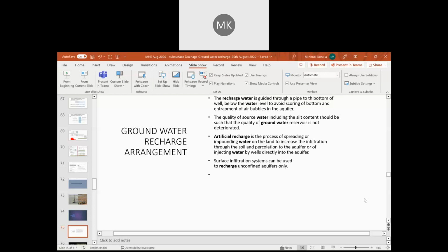So, as in these two images, the right side is a common aggregate drain and the left side is a drainage geocomposite. Definitely with the drainage geocomposite, we will be achieving increased efficiency and saving of materials. Let me skip now because we have talked enough about drainage composite and its advantages.